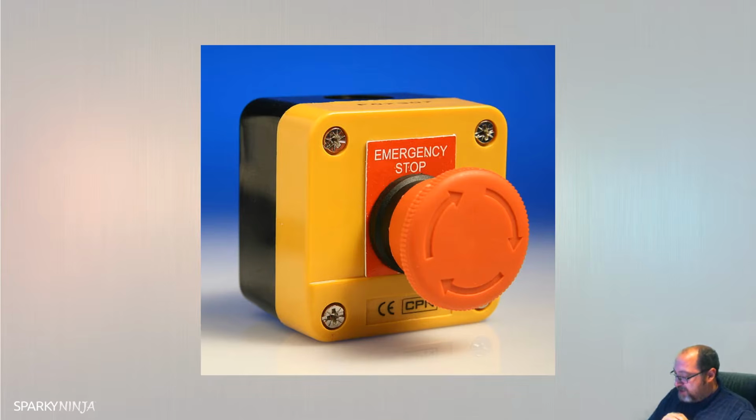The arrangement of the emergency switching shall be such that this operation does not introduce a further danger or interfere with the complete operation necessary to remove the danger. So once you've isolated it, another danger should not be introduced, and isolating it should not create a danger for the remedy process.